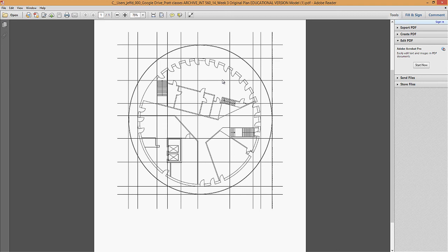If you don't have the option for the Adobe PDF, you can also plot the drawings using the DWG to PDF option. However, you might run into issues when printing your title block. That's a future assignment. With the DWG to PDF, that printer tends to have a larger non-print area around the border, and you may need to adjust your title block accordingly if you plan to use that plotter often. So this will make more sense later on.